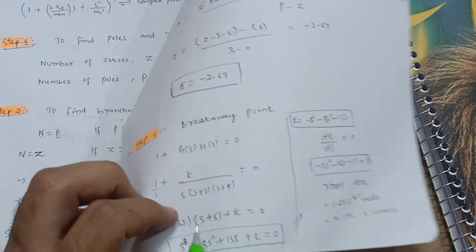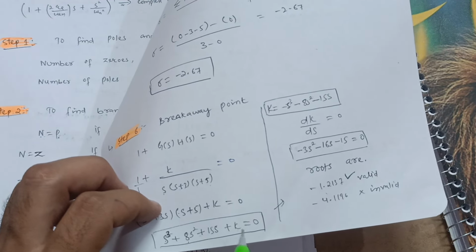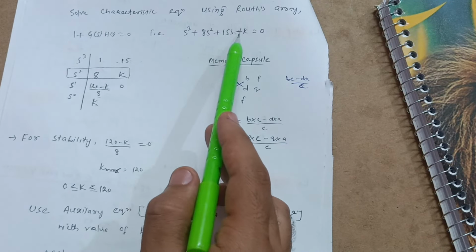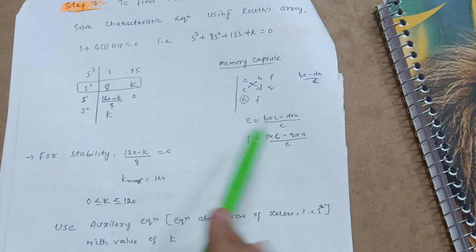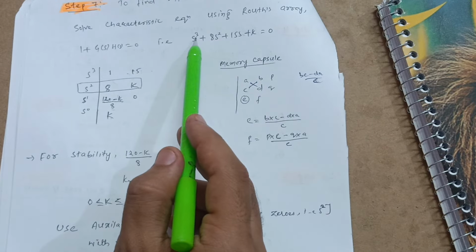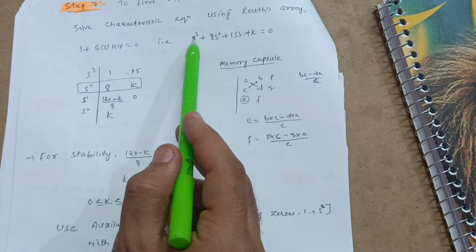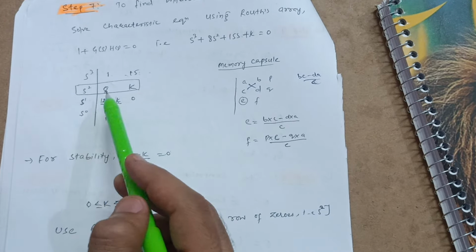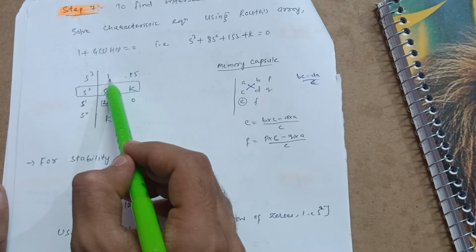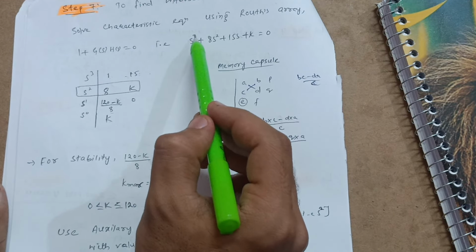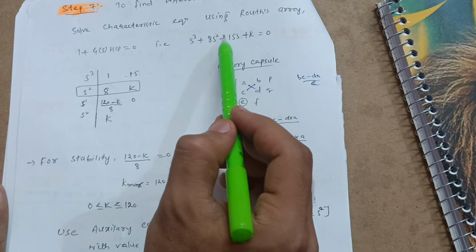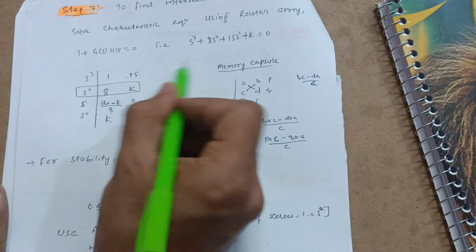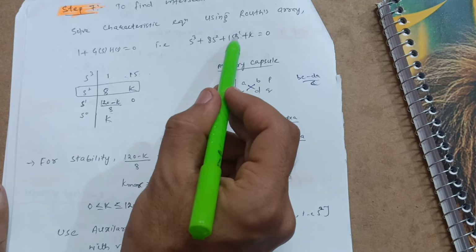where you are getting already here the characteristic equation. See here, this is s cube plus 8s square plus 15s plus k is equal to 0. You have to take this equation only, s cube plus 8s square plus 15s plus k is equal to 0. So take in the highest order first of all, sorry, descending order. You have to take first s cube, s square, s1, s raised power 0, like that. So what is the coefficient of s cube? 1. And you have to take first, if you have taken s cube, that is the odd term, so another odd term is s raised power 1 here. So what is the coefficient of s raised power 1? That is 15. You have to check first the odd values accordingly.